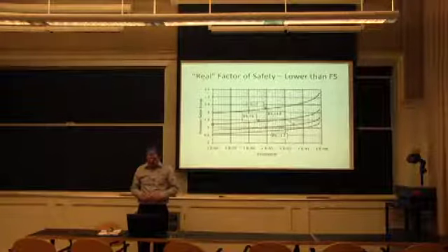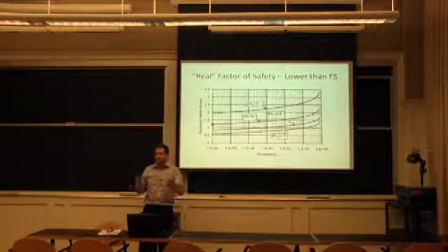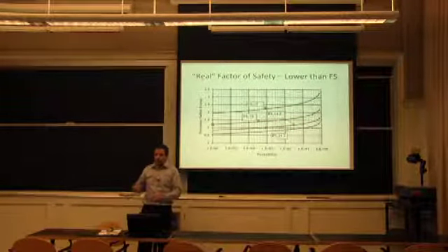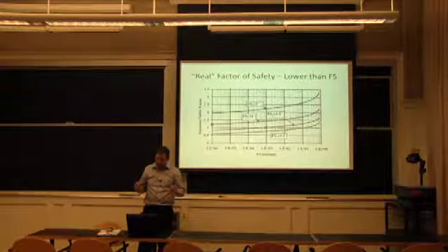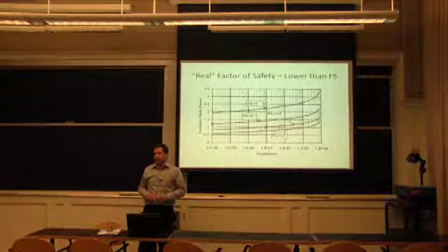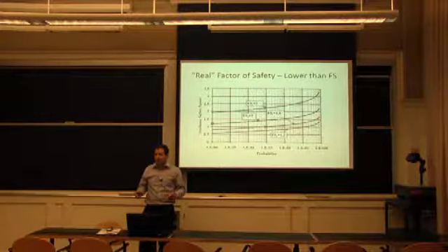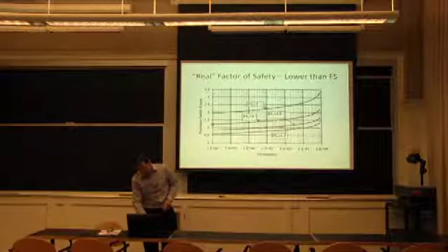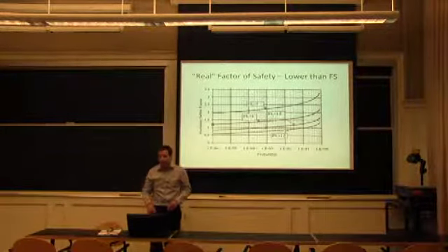And we come back, everything is fine, but as this product goes through a life, it may get beat up, in a certain area, get some scratches, and you do need to know that your factor of safety is going to come down. And therefore, depending how long you expect this to be in service, you have to start with, maybe you can start with a 1.2 safety factor. That's the popular shaft, more or less.